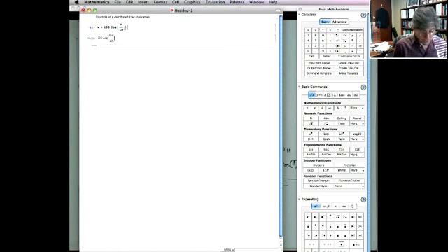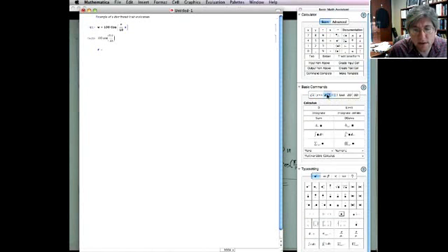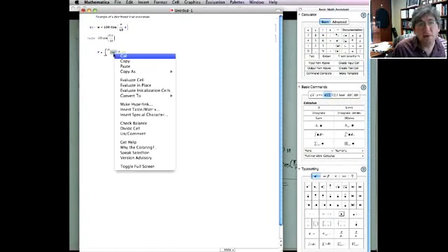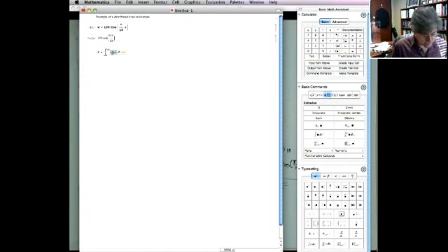Now to perform the integral, let's say f equals integral. I usually pick the little integral sign off on the right, so expression in here. The expression is W. Whoops, well, that's the lower limit. So 0 to 10. You have to keep track of units yourself. It can do units, but it's really hard. The expression is W dx. Evaluate it, and it gives me 0.